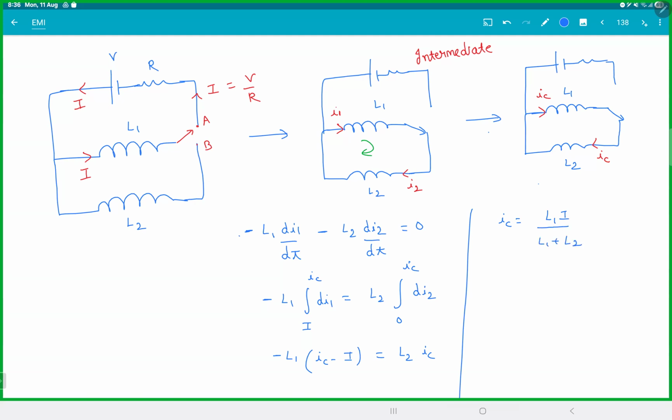So both the inductors will find this, and eventually they'll establish at this value. And during this process, you also get some heat. Heat will be E initial minus E final. So initial energy will be half L1 I square, that is energy in the initial inductor, minus half L1 plus L2 I common square. If you subtract them, that will be the heat produced.